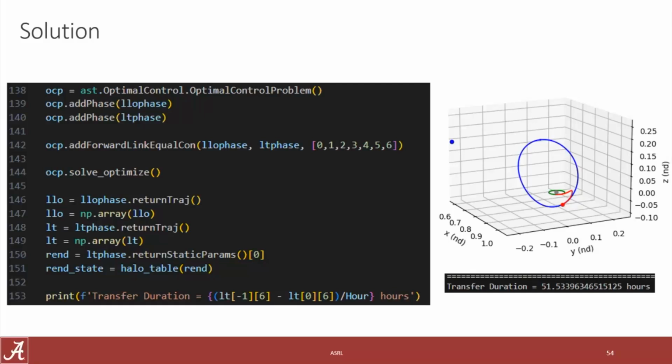So now how we've got our problem transcribed, if the optimal solution is to deploy our low thrust vehicle a little bit further around in that low lunar orbit, there's a constraint on those links that the start of the next phase must be the end of the one. So naturally, the way to optimize it is to increase the time that you're propagating the low lunar orbit out. So here we have forced continuity. Now that continuity is enforced, we can solve, optimize, and we get this transfer.